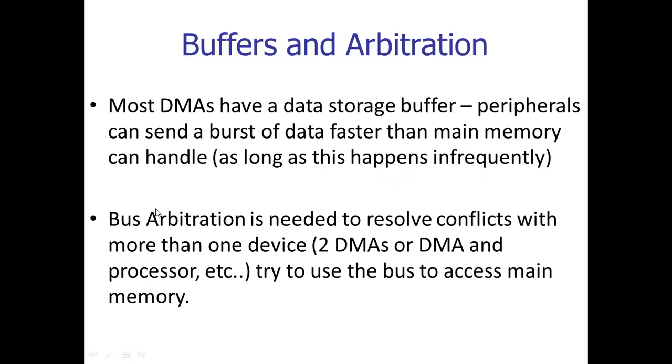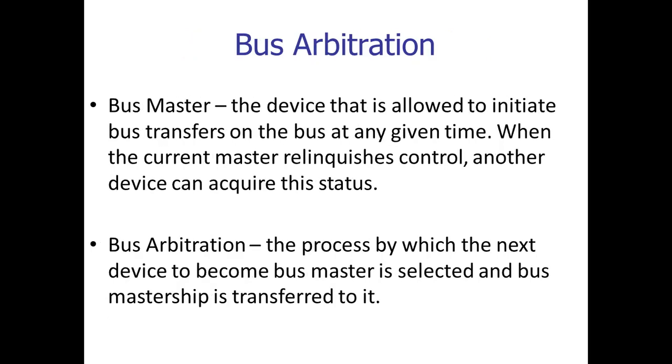Bus arbitration is needed to resolve the conflict when more than one device tries to use the bus to access the main memory. The bus master is the device that is allowed to initiate a transfer on the bus at any given time. When the current master relinquishes control, another device can acquire this status.